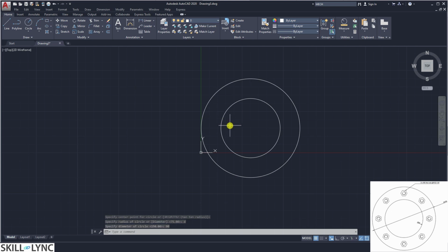Now let us draw the hexagonal nut. To start off with the nut, the dimension required is an M8 bolt with 1.25 pitch. This M8 is a metric measurement of the nut. So the nominal dia of this nut will be 8 mm, and so the across flat.